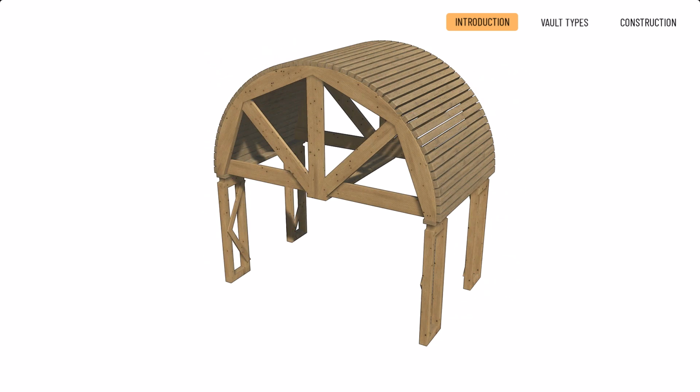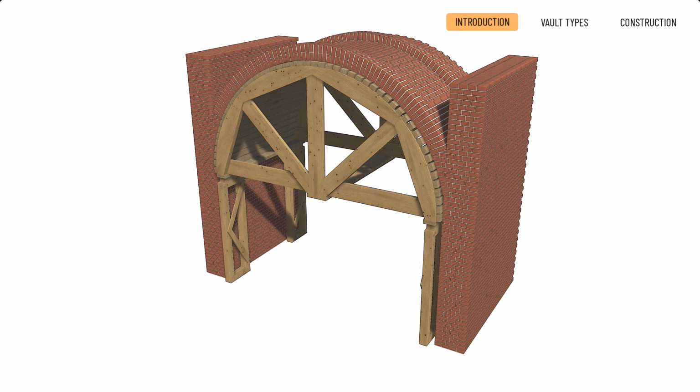Vault construction requires the use of a template, usually made of wood. It can be dismantled when the vault is completed, but even the construction and dismantling is labour and material intensive. Modern slabs completely replaced vaults from the end of the 19th century. For aesthetic reasons, you may still want to cover your space with a vault. In such cases, the vault is often made of reinforced concrete.